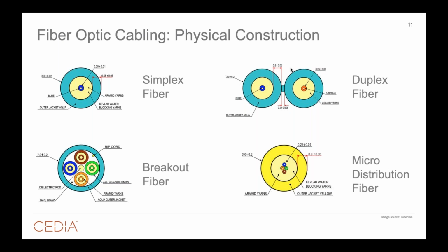That's what fiber does. Now, the difference between a multi-strand breakout and a multi-strand micro distribution is how much jacketing we're putting on those inner strands. Breakout cable, these are heavily jacketed, okay? So think of the application where we're running our trunk cable up maybe a utility pole, we're unzipping it, and we're going out to 2 different security cameras. That's a great application for a breakout fiber. Heavily jacketed, not quite as easy to run because we're dealing with a lot more jacketing compounds and thicker jacketing compounds.